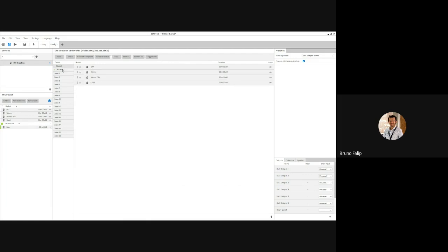So when you're done with that, this is a place where you can unselect the loop. You can see by default they are looping. Make sure you select one loop only for your DALI scenes to avoid the scene looping and sending the same command again and again. I think in future we will automatically specify one loop only for DALI scenes. It would be easier for you to manage.